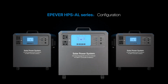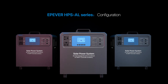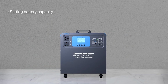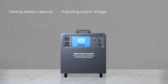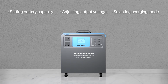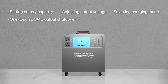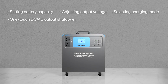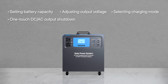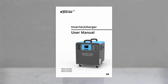In this video, we will demonstrate how to configure the device by using the built-in LCD display unit. This includes setting the battery capacity, adjusting the output voltage, selecting the charging mode, and performing various operations, such as one-touch, DC and AC output shutdown. Please note that this video is for demonstration purposes only, and for detailed settings, please refer to the user manual.